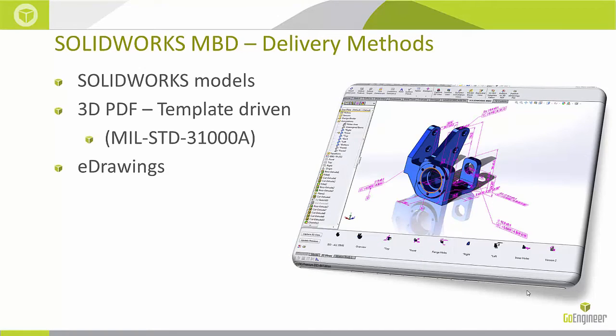SOLIDWORKS MBD is a little bit unique in that we have 3 different delivery methods. We have the actual SOLIDWORKS model, where we capture that design intent and produce our designs. We have a 3D PDF that's template driven. It's a little bit different than what we've had in the past, and this is what allows us to comply with MIL-STD-31000A. And then we have our viewer, eDrawings, which has allowed us to convey that design intent throughout our organizations over the last decade plus. Those are the 3 different delivery methods we work with in MBD.